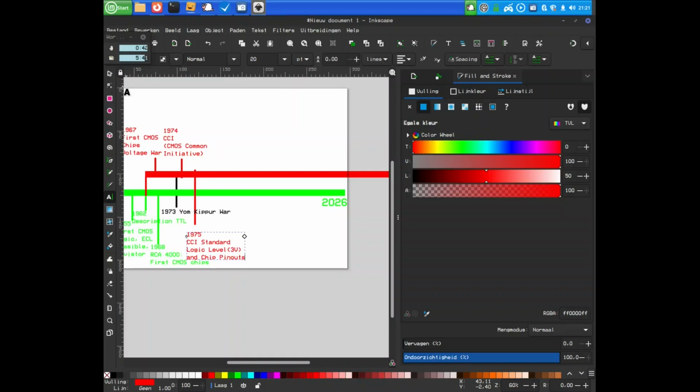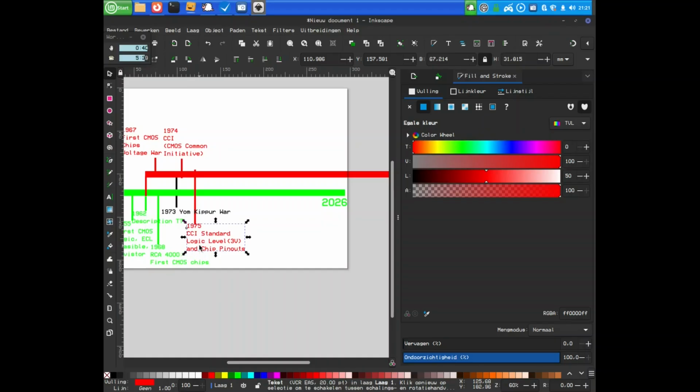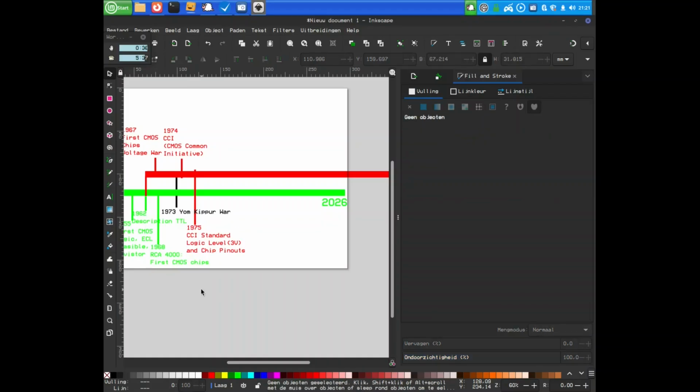That would basically mean that the pinout of a chip would determine whether or not it could be used with another similar type of chip. If the pinouts are radically different, you'd have to rewire your entire circuit. However, CCI chip pinouts for certain common chip types, not including CPUs and graphics circuits for now, would have allowed many of the glue logic chips to be standardized so that you could easily swap them out. This would make life, especially for hobbyists and in the military, a lot easier.